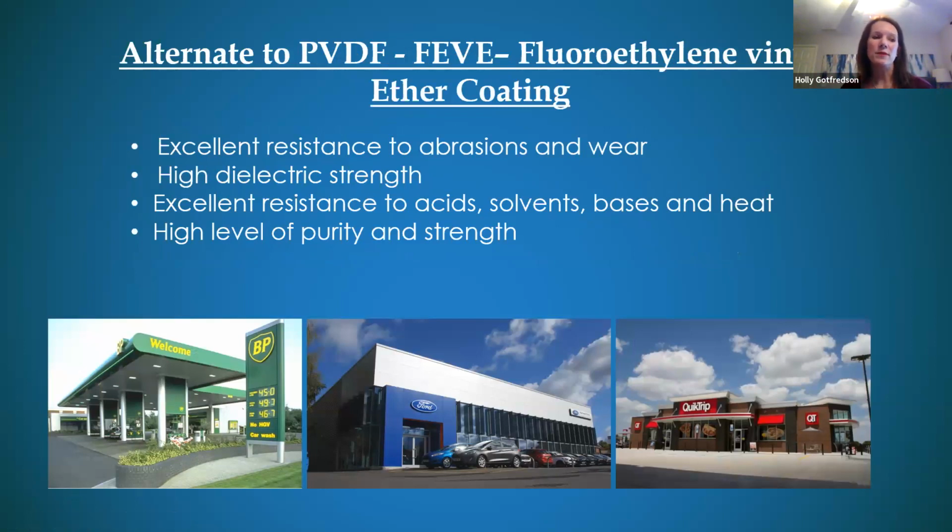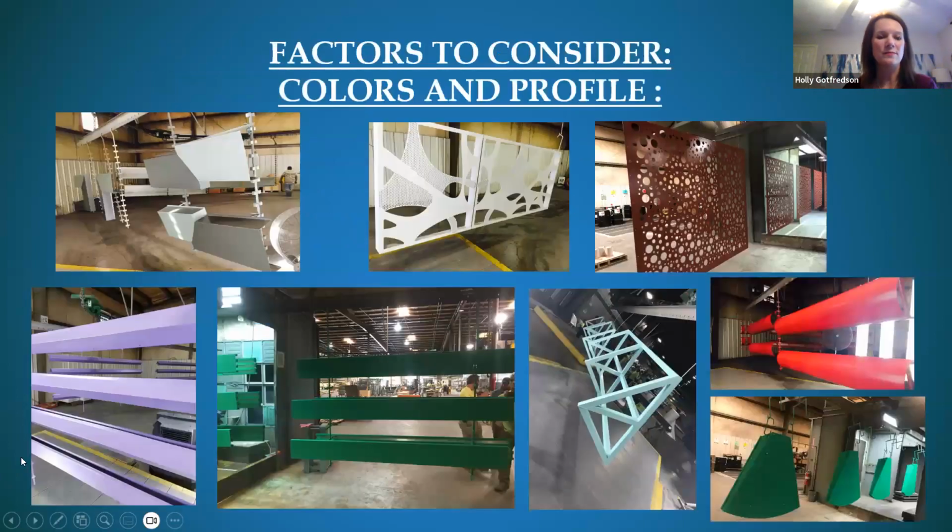During the pandemic, when there was a shortage of PVDF, we pivoted and discovered another capability that we could offer. So when maybe PVDF was going to take too long to get in, we could also offer FEVE. Some more words I can't say, but FEVE is a great coating. It has a little bit more gloss to it. Now, I will say it's 15 to 30% more expensive than PVDF, but if you're really looking to get a bright, vivid color, maybe we can't find something in PVDF that really is to your liking, this may be another option for you. So again, just a great conversation to have as you're thinking about schematic design and then getting into construction documents.